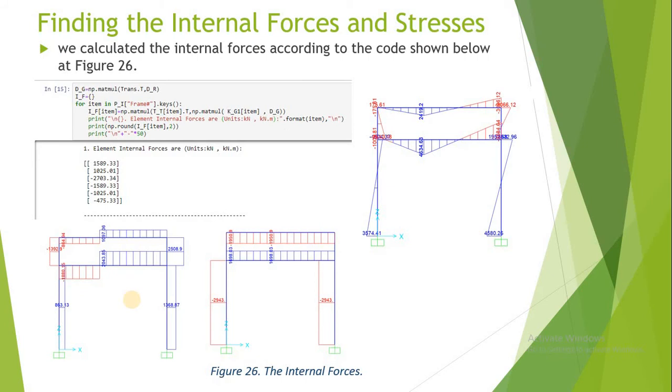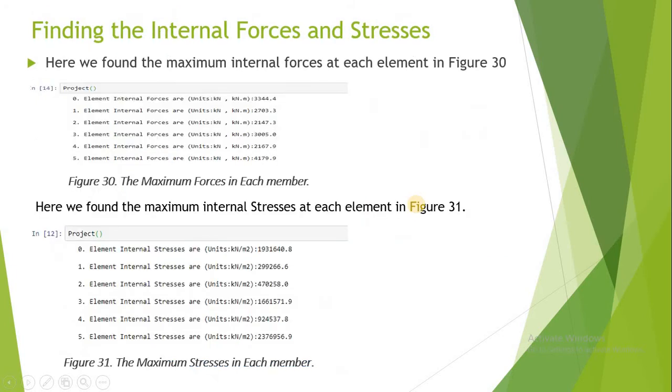After that we find the internal forces and stresses. Here are the element internal forces for each element, for example for the first element, and here we attach the internal forces for each element: the shear force, the axial force and the bending moment. After that we find the maximum internal forces in each element and also the maximum internal stress at each element.